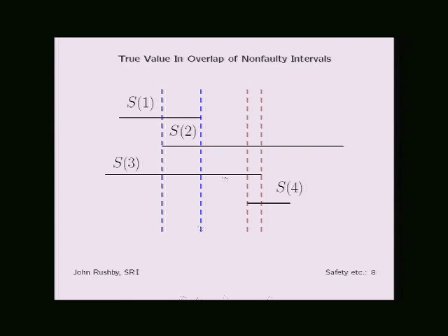So suppose your algorithm requires the sensor reading to be somewhere in the blue range, and you have a test on that value, right? So let's say the left blue end is 1 and the right blue end is 2. And you have a condition in your code which says if the sensor value is between 1 and 2, do this. Otherwise, do something else. Right? If you have this big interval, you can't tell whether the sensor value is between 1 and 2 or it's outside the interval. And so making decisions on sensor values becomes much harder.